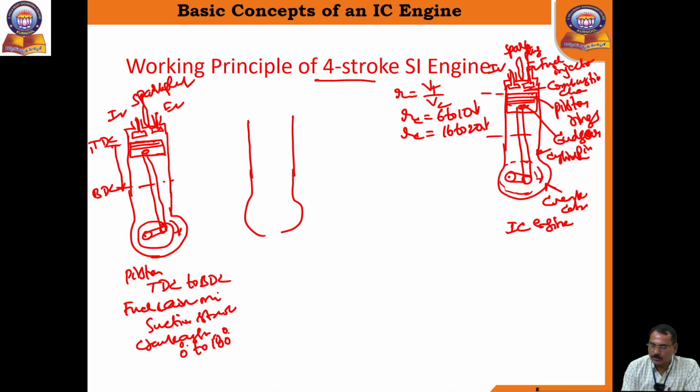During compression stroke, the piston moves from bottom dead center to top dead center. Same components available here. I mean inlet valve in this case closes. Inlet valve, exhaust valve. Both valves are closed during compression stroke.